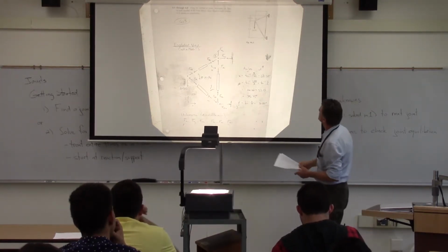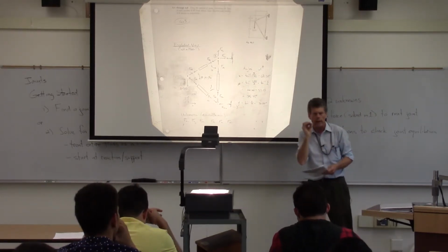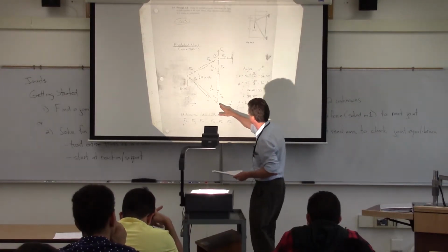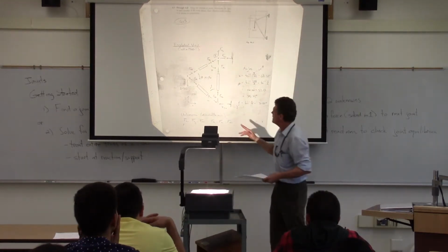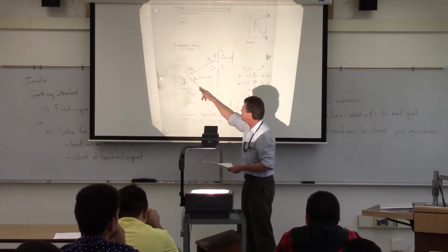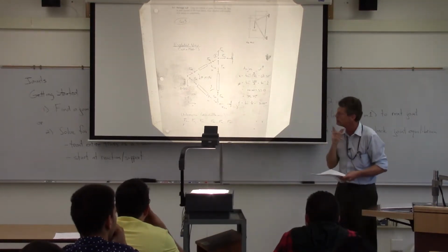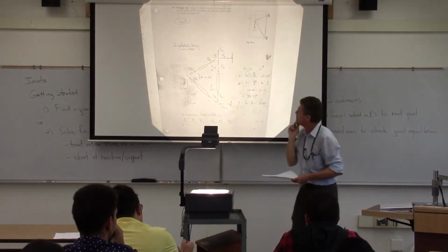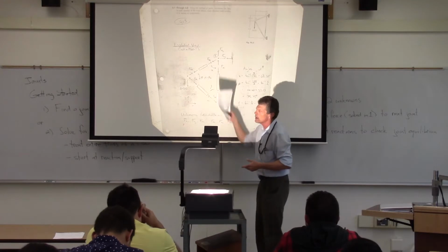And then there's some quick calculations since they didn't give you any particular angles. Again, when we think about this, what we're going to be doing now in our method of joints, we talked about it being particle equilibrium. What I'm going to be doing is looking at these particles. So these are the joints that I'll be looking at, knowing that if I solve for a force in this direction, pushing this way, then I solve for my member force. I know that that member has to be in compression by that same magnitude. If it happens to be pulling at the joint, I know that in my member then, the member will be pulling back basically because of Newton's third law there. I'll have a member in tension.